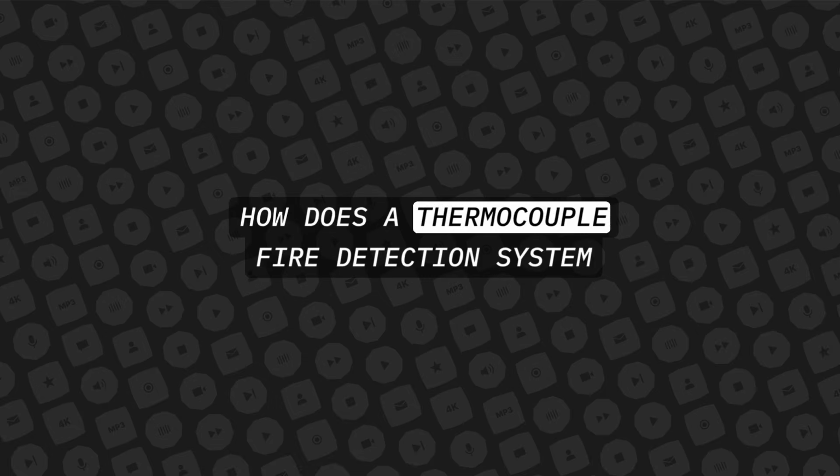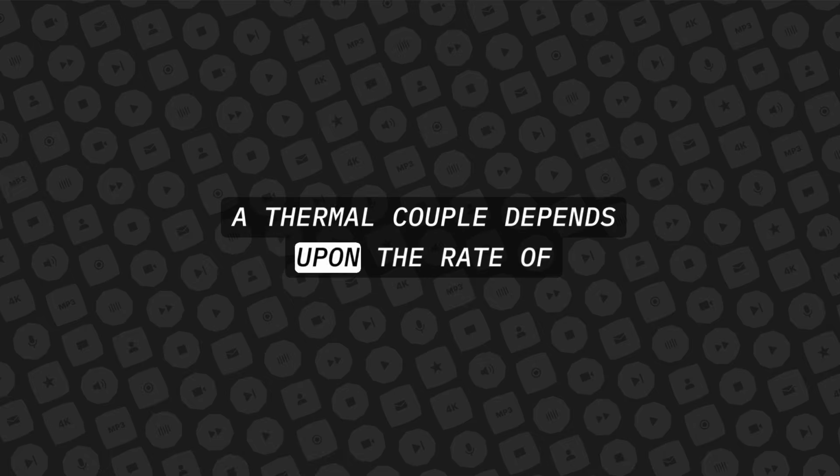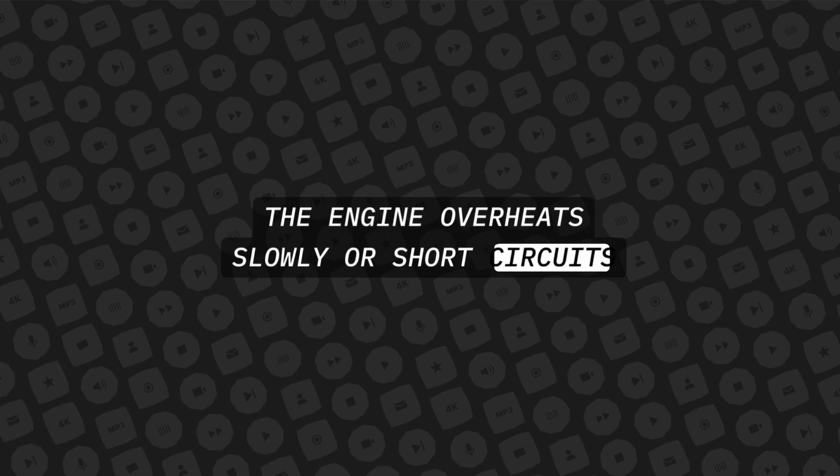How does a thermocouple fire detection system differ from the thermal switch system? A thermocouple depends upon the rate of temperature rise and will not give a warning when the engine overheats slowly or short circuits develop.